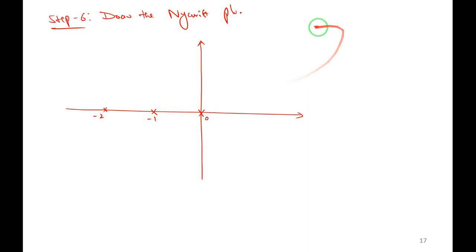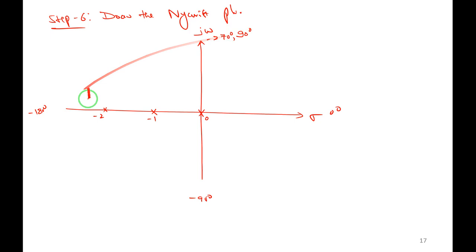And the critical point. What is the critical point? Sigma at j omega. 0 degree, minus 90, minus 180, minus 270. If I go in the anti-clockwise direction, this is 0, 90 degree, and this is 180. I will not write it all, but I require this, so I am writing 0, 90, 180, 270 like this. I hope you are getting it. Please concentrate on the critical point. It is minus 1 plus j0. This is the critical point, here at the same point.